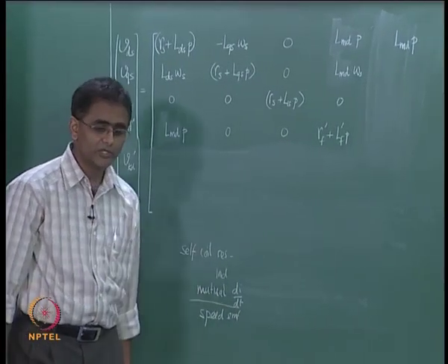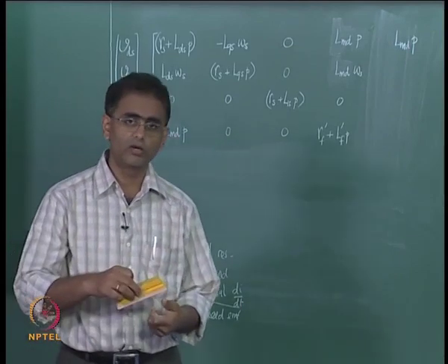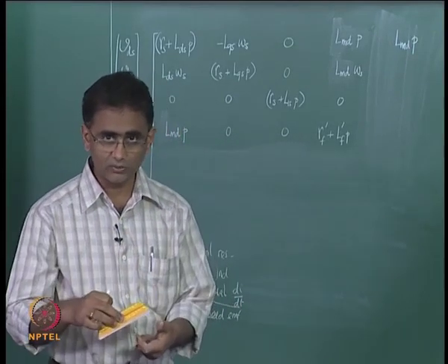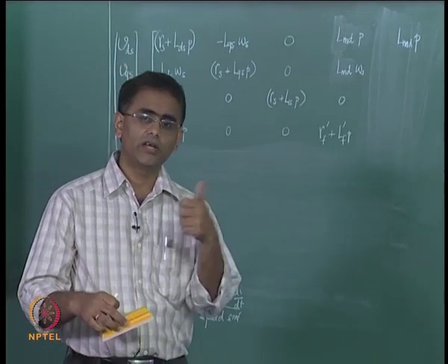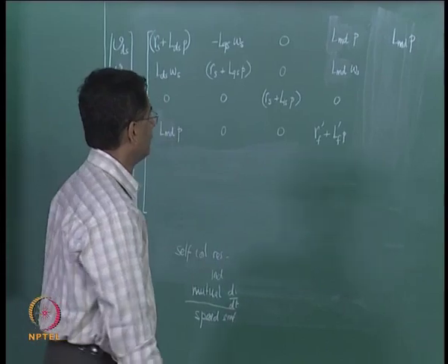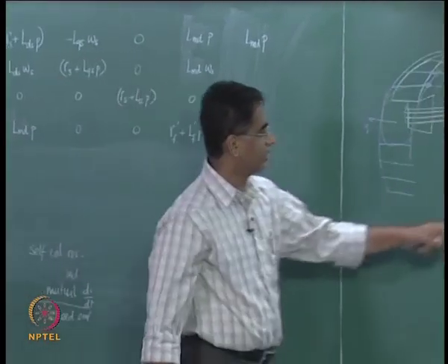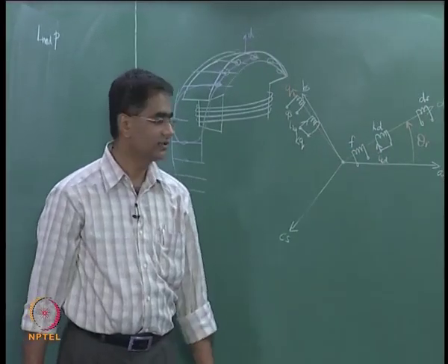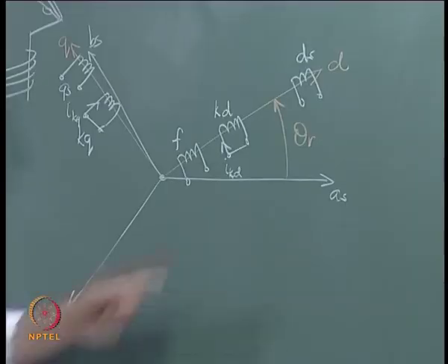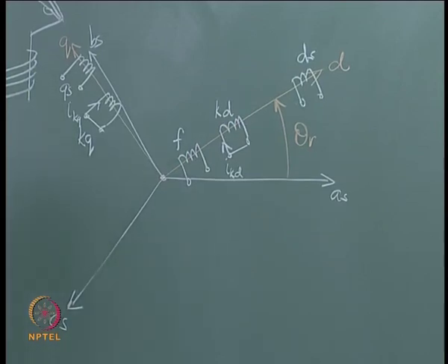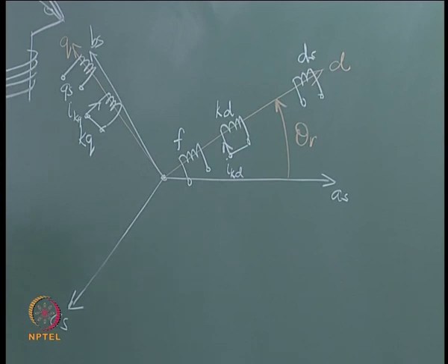Speed EMF terms arise in one coil, provided it is a fictitious one, from the excitations on the axis 90 degrees away. Now in this case, we are looking at the equation for the ds term, and this coil is definitely a fictitious coil because it is a representation of actually fixed coils on the stator.